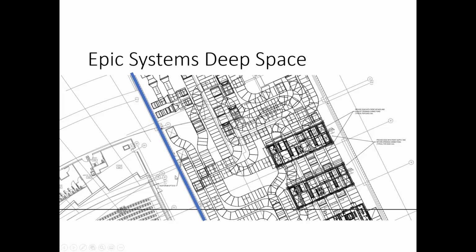There's an expansion joint between these 2 sides. So there are no rigid connections between the structure of this and the structure of this. So that helped us to still get the really low noise levels and eliminate the vibration like they wanted.